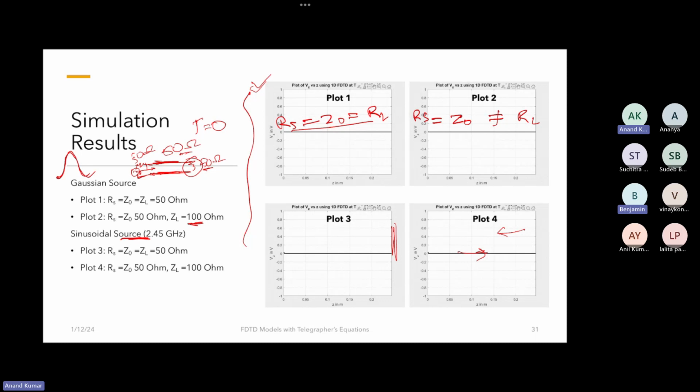Just a question, Prof. Yes, Benjamin. You are discussing the case on the boundary conditions where you've got a perfectly matched layer, like a PML. What happens in a case where you don't have a PML, or maybe you've got a PEC material? Because sometimes when we do simulations with antennas, sometimes you are using PEC and sometimes you are using PML.